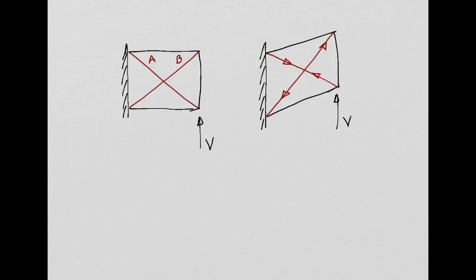So when you deform these two struts, strut A, basically the final length of strut A will be smaller than the initial length, so it means it is going to be compressed. And strut B, the final length, so if you want this length here, is going to be higher than the initial length, this one, right? Yeah. So it means strut B was stretched, right? So basically strut B is going to be in tension, while strut A is going to be in compression, yeah?